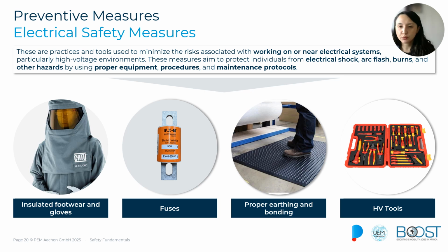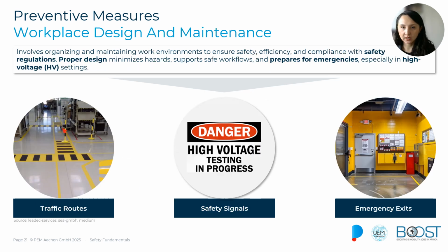One general and practical tip is that when we are working with electrical systems, even if they are high voltage or low voltage, we always have to treat equipment as live until it is proven otherwise. Never assume that a system, a socket, or a battery is not energized unless you have personally verified it and you have used the appropriate testing tools to verify that. That is a practical tip that we have to follow also.